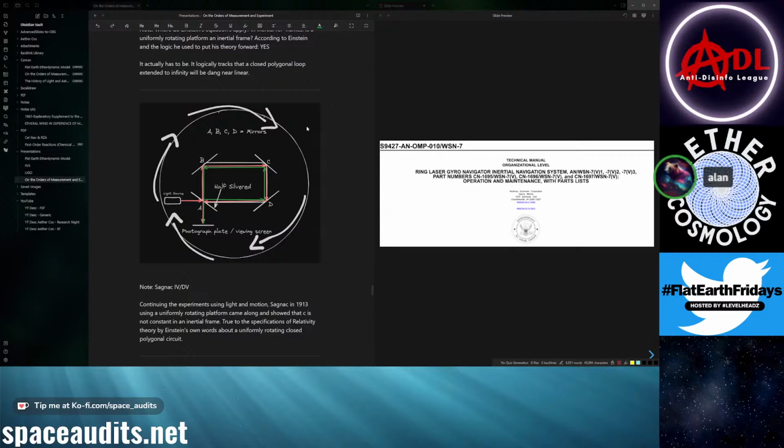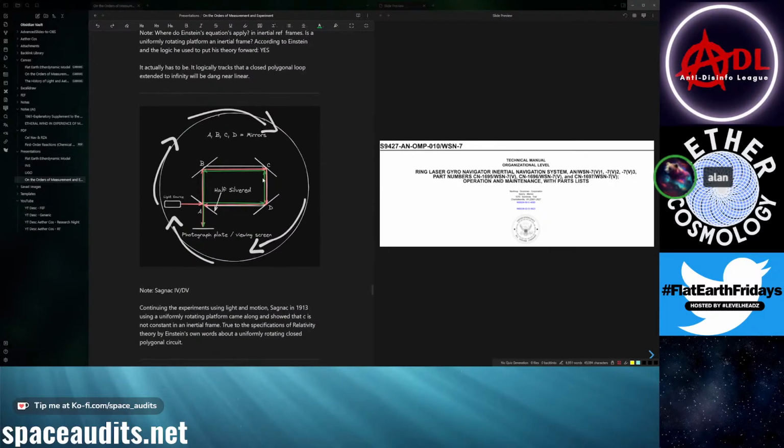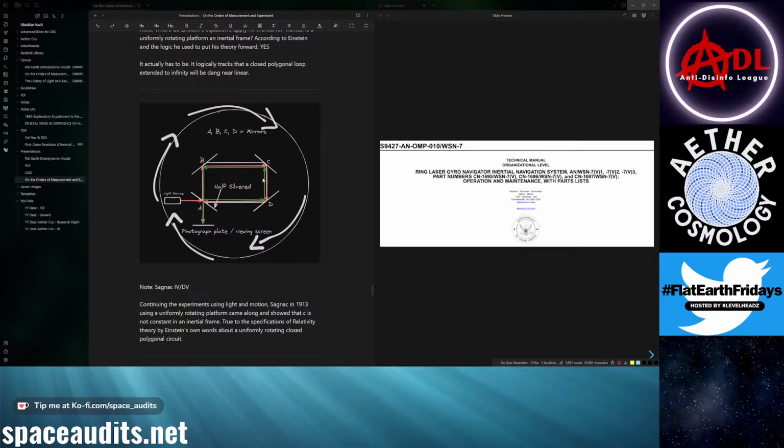There will be an additional variance added, in a sense, it's basically like a velocity addition, to be honest with you. So however fast this is rotating, it's going to produce a fringe shift pattern proportional to that rotation. In addition. Yep. So then when it's attached to an airplane or whatever, and that banks, that velocity is going to get added to that, and it's going to cause a further displacement in the fringe. And they take the difference in that, and they go, okay, we're going at 700 miles an hour or what have you, right? Right. Gotcha.